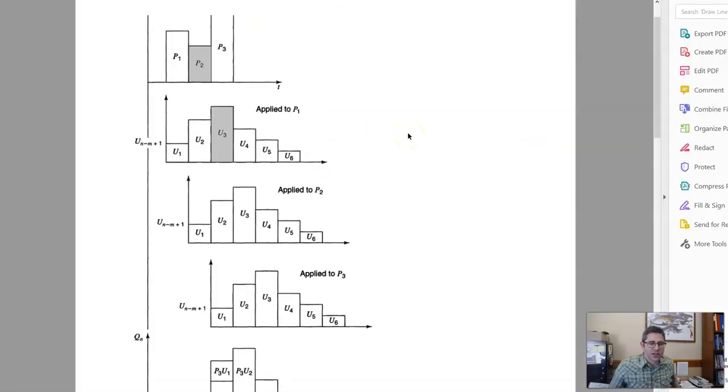And some figures. These are some figures from your book, where we see a simple rainfall hydrograph up on the top. Precipitation P1, precipitation P2, and P3. So 3 different time intervals, 3 different intensities. What I'm going to do is take my unit hydrograph, which is this figure right here, and apply it, starting at the beginning of the storm, essentially to just this interval.